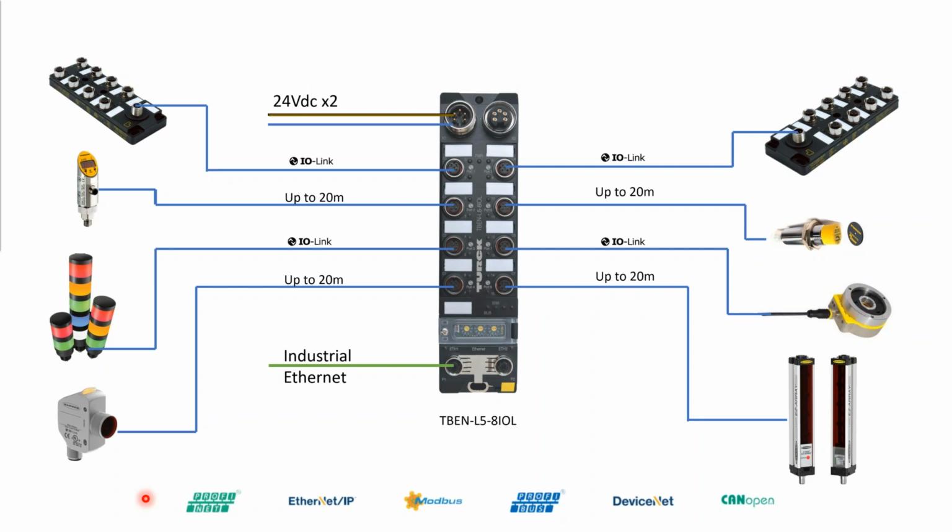And historically, you got a lot of empty ports because I might only have 1 analog device. So now I have to go put an IP address out there for 1 analog sensor. The other issue you might run into when it comes to indication devices like this incredible Banner TL50 tower light, this is a 3-color and an audible. So 4 outputs required to operate this device. Where if you're using your traditional IO block, you're only going to get 2 signals on each of these ports.